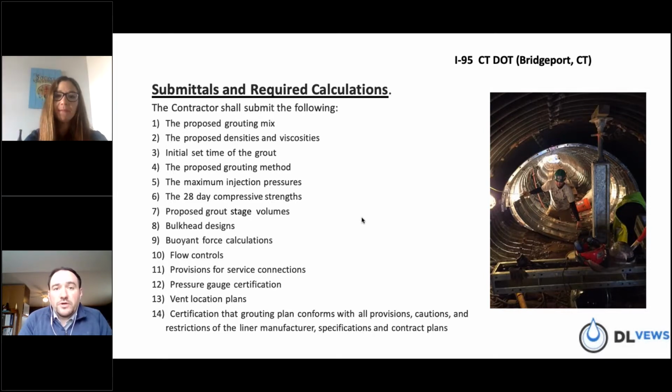So let's say, for example, you're in a 72 or an 84-inch corrugated metal, and you have the ability to get in there and just use some channel iron and connect your PVC tubes ahead of time, and you slide your liner pipe and you start grouting. That's one way I can think off the top of my head to go ahead and speed up that grout process, or getting ready to grout.